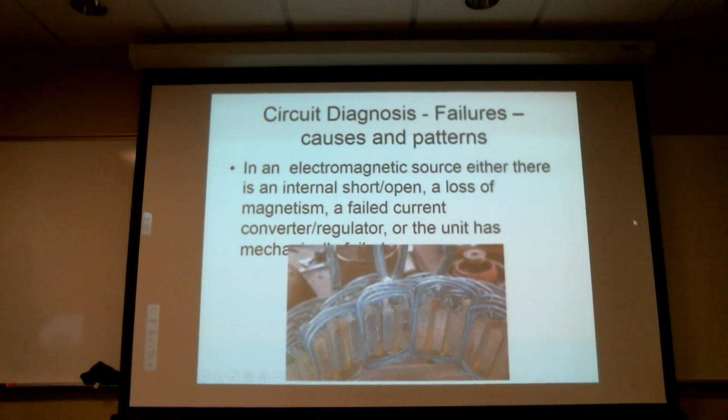Now sometimes these fail mechanically. When they do, it's usually the commutator brushes, something's wrong there, or a bearing starts to go. If it's a bearing, you can hear it. You may not be able to tell where it is. You've got a big engine running, and you can hear this.